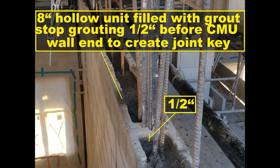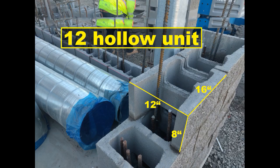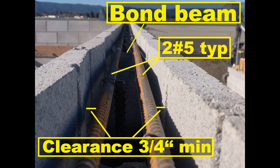Solid load-bearing units, ASTM C90, normal weight units. Solid units shall be provided as indicated in drawings. CMU unit typical dimension of 8, 10 and 12 inches wide, 8 inches high, and 16 inches long. Precast concrete units.